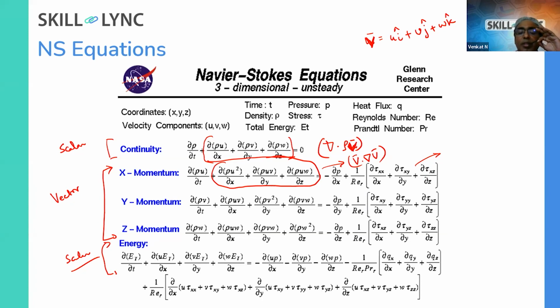So this is the general form of the equation, and this is the energy equation. Again, you see, this is nothing but your pressure gradient term. This is your heat conduction term, so this is a diffusion term. This is the work done by viscous forces. So energy, this is nothing but the work, right? If you remember the energy equation, it is derived from your first law, right?